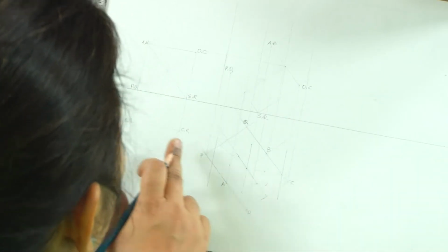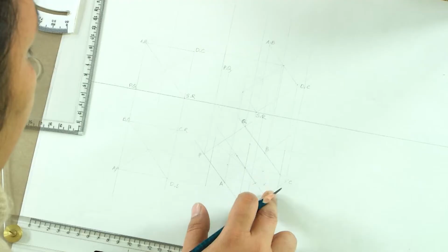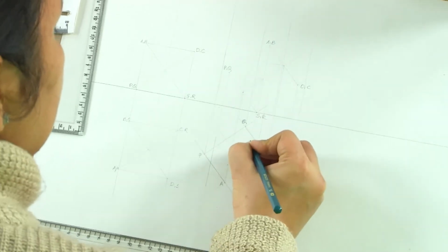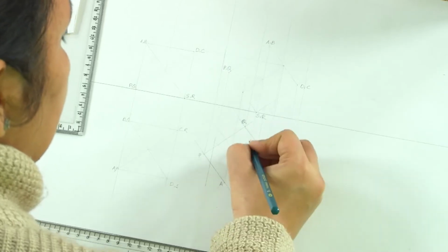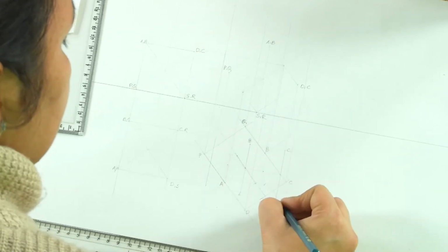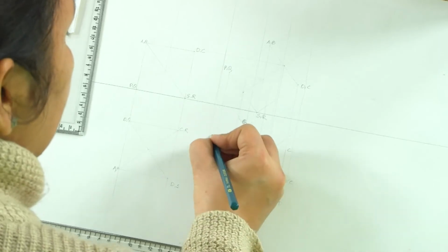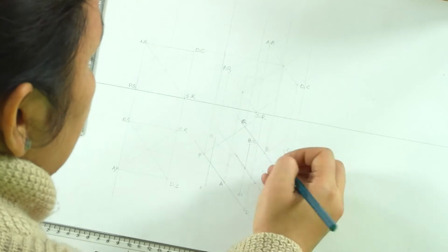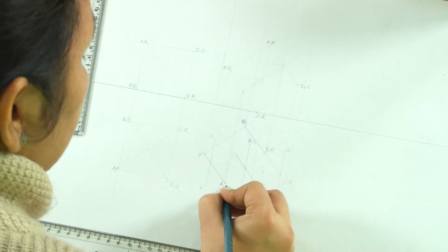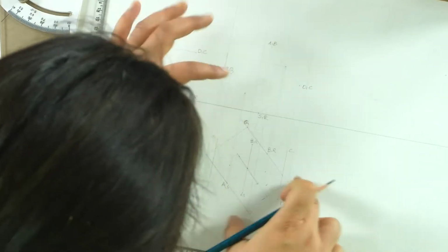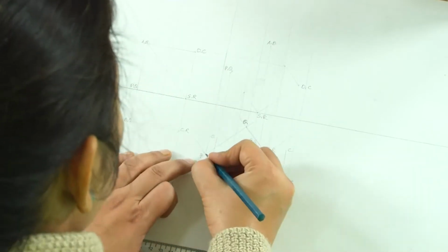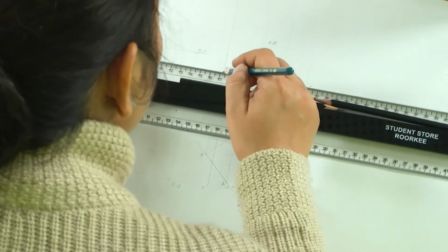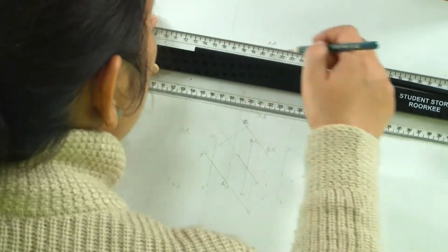So, if you look at the original picture before we rotated it further, what did we have? We had A, B, C, D, and we had P, Q, R and S. The same thing has happened here. So, we have R and S here. Now we will take it back. The P goes and meets P, so the horizontal projections have remained the same.